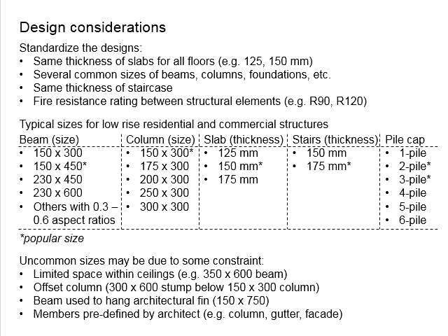Again, you have to consider the fire resistance rating between the structural elements. This was a mistake from my students, that some elements have a fire rating of 90 minutes, while some others have a fire rating of 120 minutes.